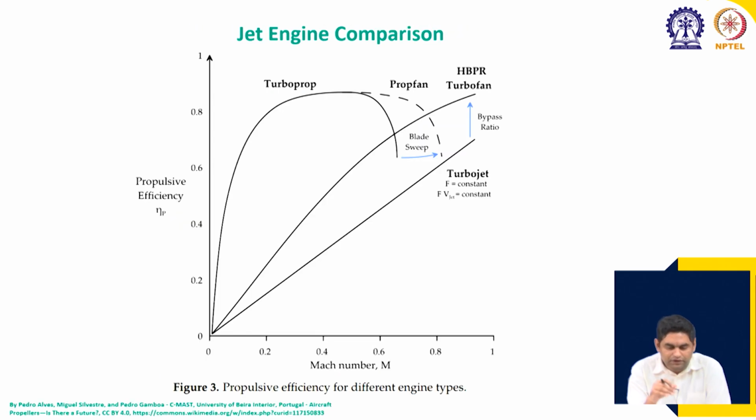So, in real life, when are these engines used? For turbojet, generally the propulsive efficiency increases at a high Mach number. So, beyond 1 we get very good propulsive efficiency if we keep on extending. Turbofan, high bypass turbofan, is used for commercial application. Low bypass turbofan will be similar to turbojet, slightly on the upper side. High bypass turbofan will have higher efficiency at moderate Mach number, but at very high Mach number it cannot be used.